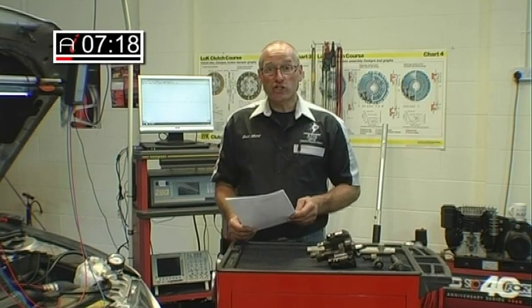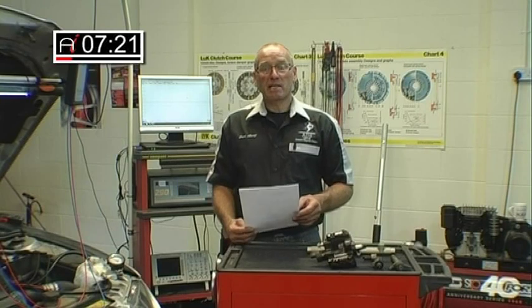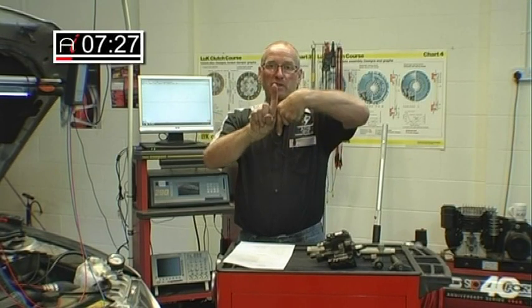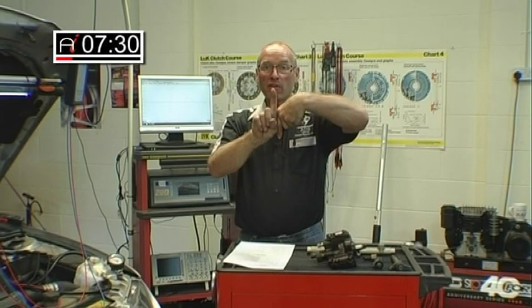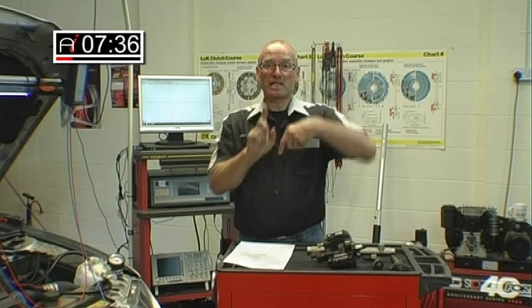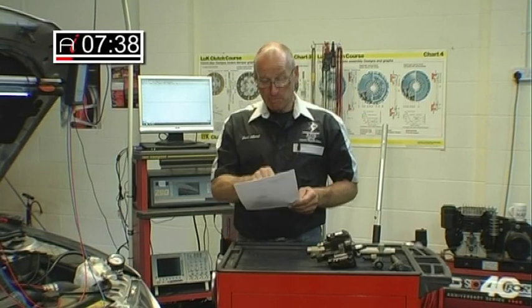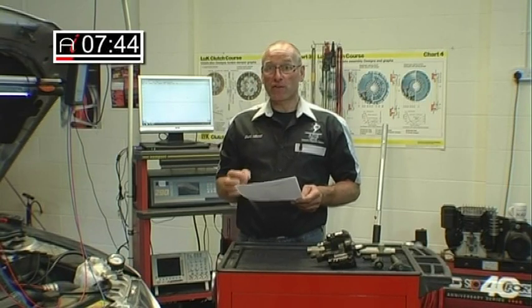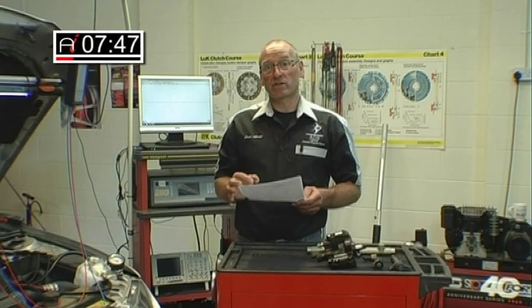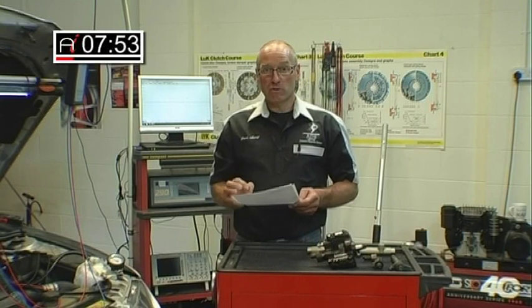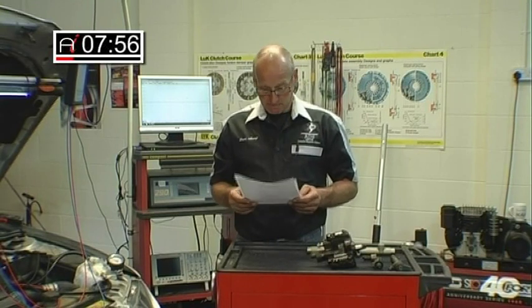So that is an issue we need to resolve. To do that, we're going to measure current. The capacitor voltage is monitored serially and is displayed as a voltage. Now the rule is voltage up, current down, voltage up. When we switch an injector off, the voltage diminishes, the current diminishes, the voltage increases. The back EMF, which is displayed on the scan tool as capacitor voltage, is in effect an interpretation of the current path and the quality and quantity of the current path through the injector. We're going to measure this as current. End product, more reliable, much more accurate. We're going to measure current flow through that circuit.